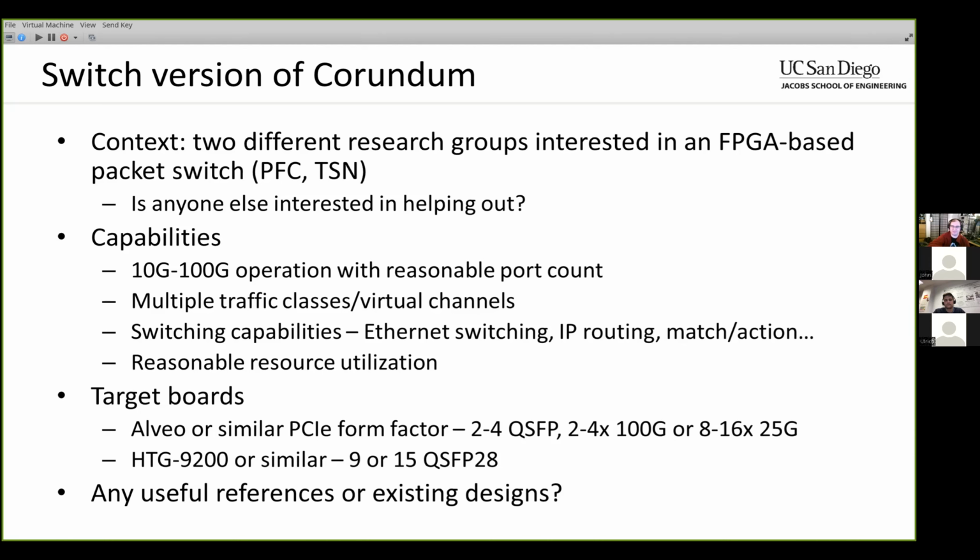So is it one block on every port? If you have 64 ports, do you replicate that block 64 times? Every port has its own local MAC address table, its own local IP routing table. I'm not sure. Is there some level of sharing? Is it like every 4 ports or something that are looking at the same resources? Because some of these tables can be pretty big, I think, at least for IP routing. And you can only put so much SRAM on a chip. You have to have packet buffers and stuff too.